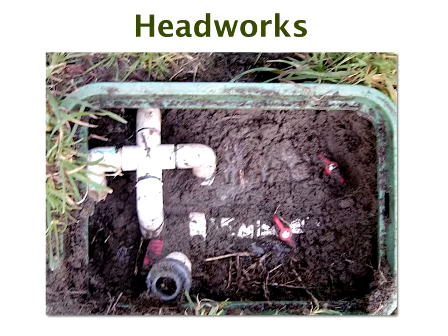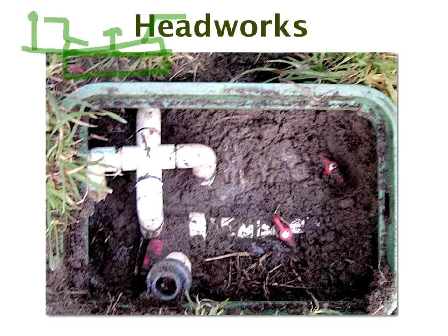Because what happens is, when you've got this in the ground, if one can imagine the ground level is here, and you've got a situation, I hope I'm drawing this a little better than it looks for me, like this, there's an open hole here and the gopher's running along here, and he's throwing up his mounds. Here he hits, oh boy, this is a beautiful, easy place to throw up his mounds because he's got very little resistance. And they throw their mound up in the box, and this is frequent. If you don't put a good layer of gravel underneath there, there's a high risk of gophers throwing this up into the box.